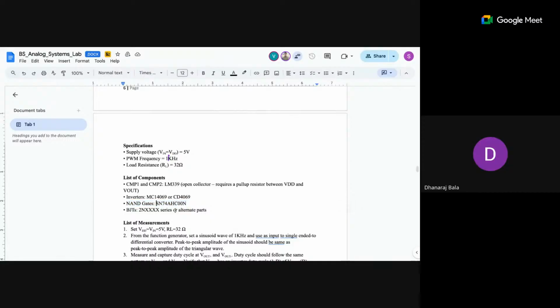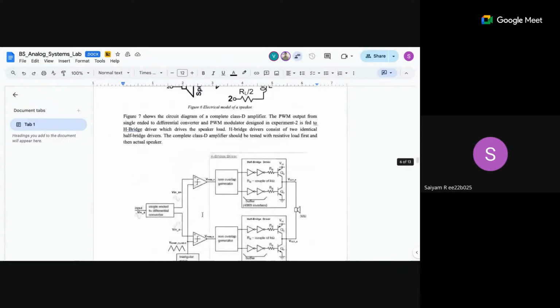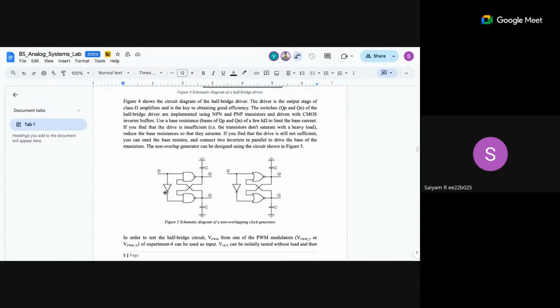Yeah, 7400. Yep. So then you have to use the NAND gate, this one. Or are there any ICs with these latches, D flip flop, right? I'm not sure about that, but I think you have to build this with the gates. You won't get an IC which directly gives you a clock generator.